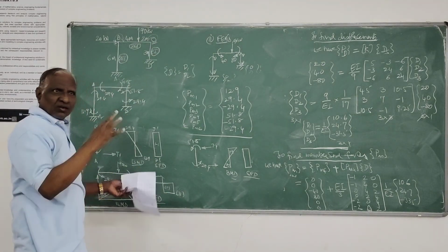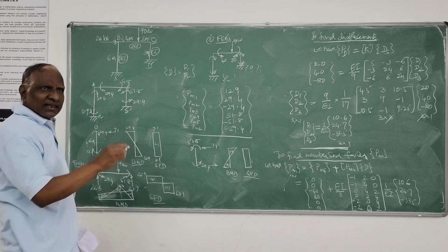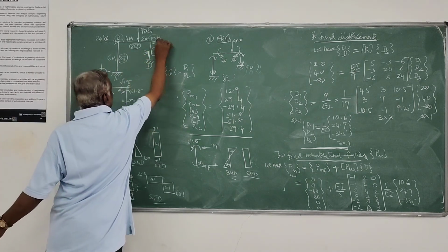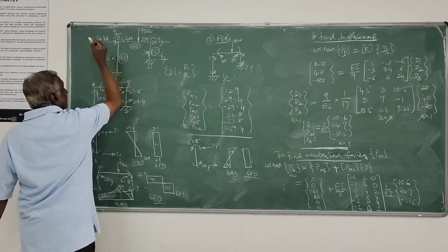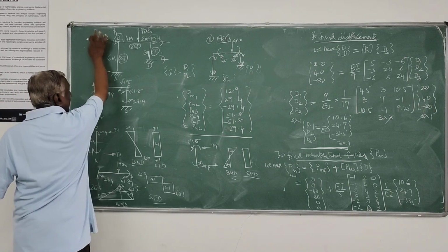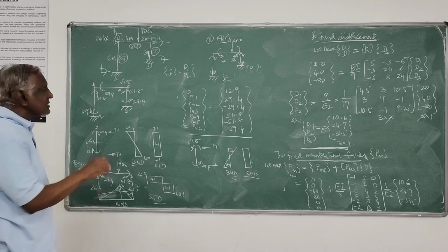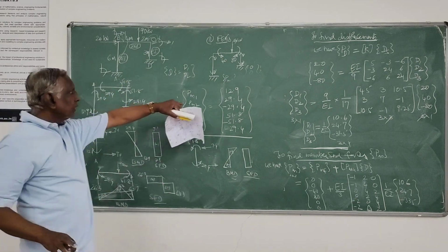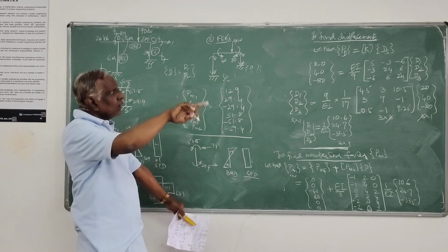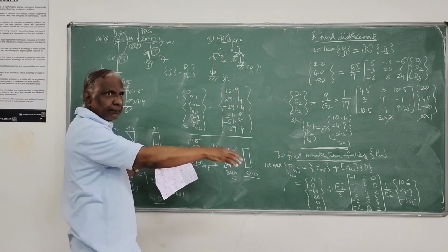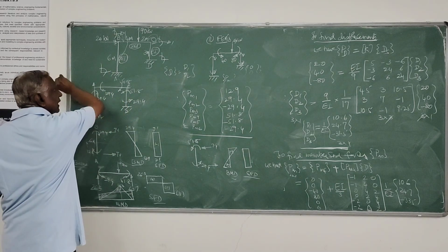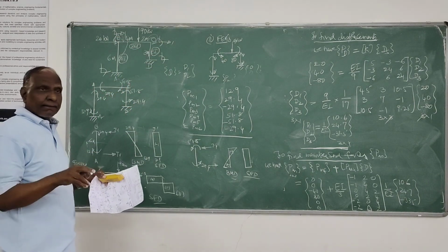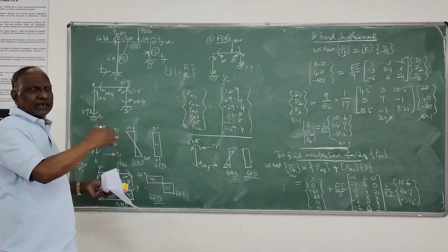That is the kinematic indeterminacy. First step, when you are determining kinematic indeterminacy, that itself is your coordinates for the displacement. I am allowing 3 degrees of freedom at each joint. Very first step you can see for the generation of the stiffness matrix. If this load is not there, but sway occurs, this coordinate you have to take because it is moving. In the computation of PD, we get 0, load is 0. But in the computation of the K matrix, we have to generate the stiffness matrix corresponding to this degree of freedom as well as two rotations. And D also D1, D2, D3. D1 is translation. D1 will automatically be whatever value you are going to get.